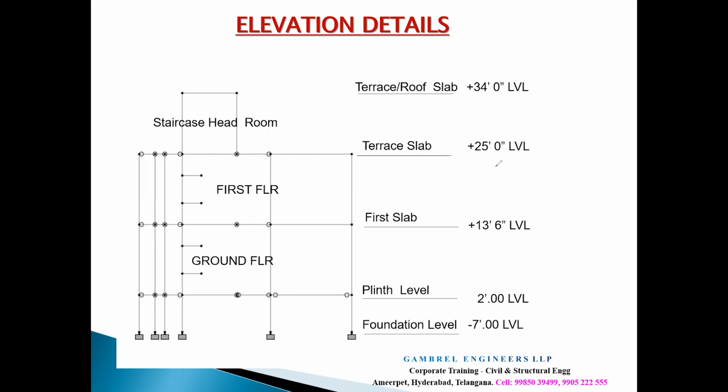If you go higher, like 12 feet height, it becomes uneconomical. But 12 feet height might be required for some hospital buildings, where additional equipment is required below the slab. Additional equipment in the sense of additional services arrangement, like a firefighting system. A firefighting system will be provided within commercial spaces or institutional buildings, right?